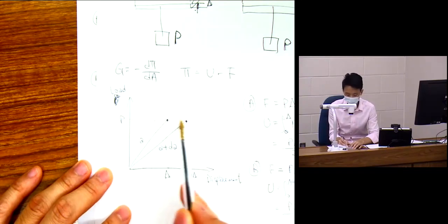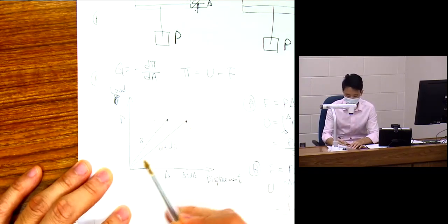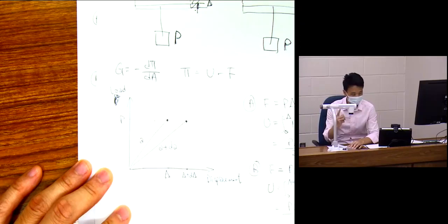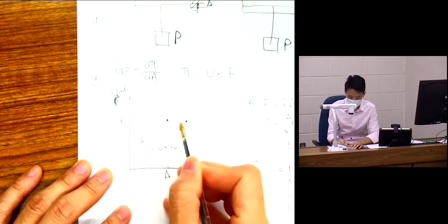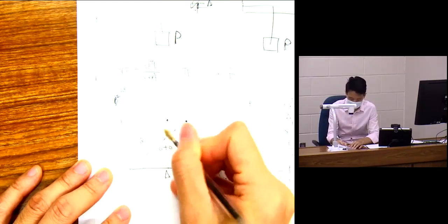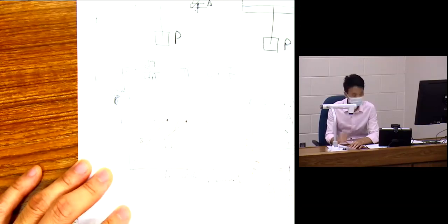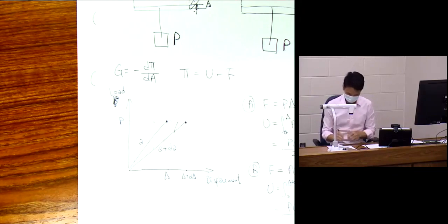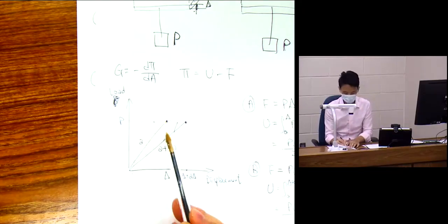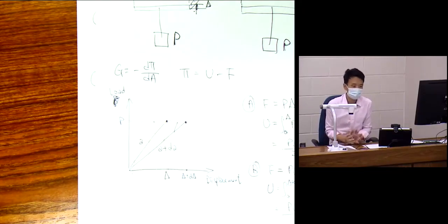Okay? Similarly, for configuration B, the larger rectangle is the work done for configuration B. The area under the curve is the strain energy of configuration B. Now, the difference of these two is the complementary energy again of configuration B, which is this triangle, right? So you can see that there are two triangles, and the triangles mean what? That is pi.